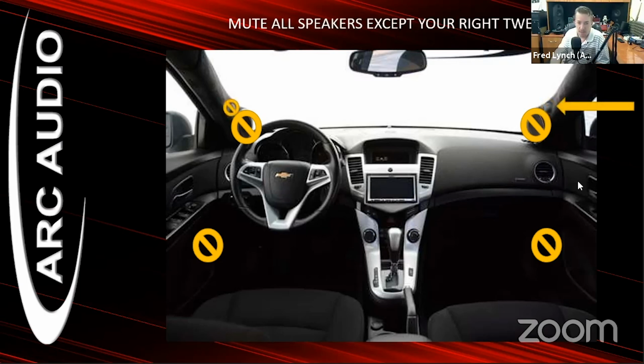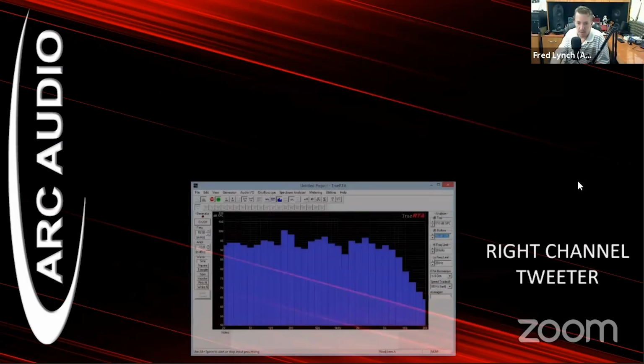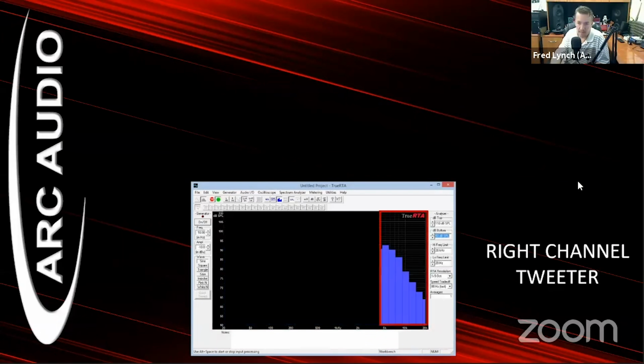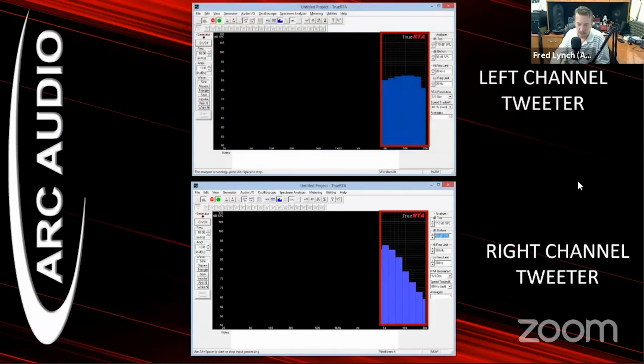So now we're going to basically mute the entire system except for the right tweeter. Now, if you remember, this is now what the right channel side system would look like. We're going to isolate that. And this is what our left side looks like after EQ. Now, what we want to do is we want to match the right channel tweeter exactly down to the dB, or within what the parameters of the meter is. We want to have this dB, or this set, from right channel to left channel match. So adjust your right channel tweeter to match your left channel tweeter. And there we go. To the driver's position, we have an identical reference response to the driver for the tweeters now.